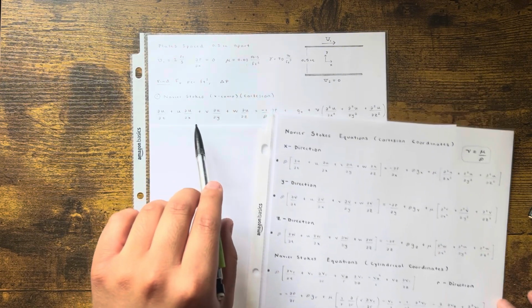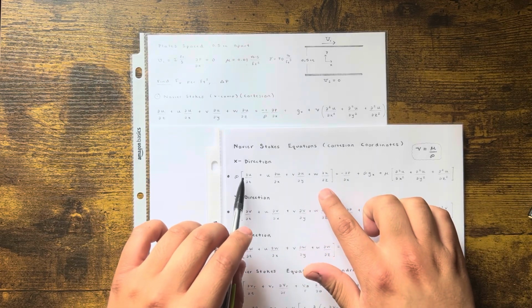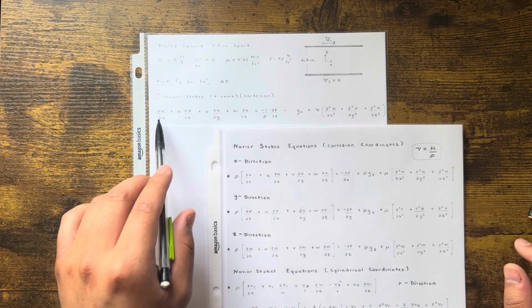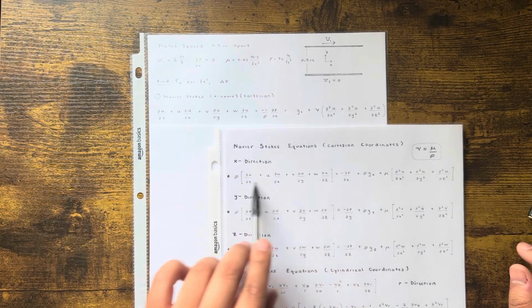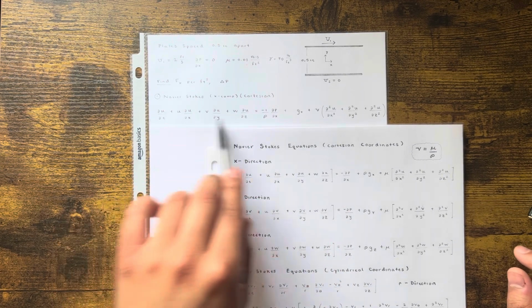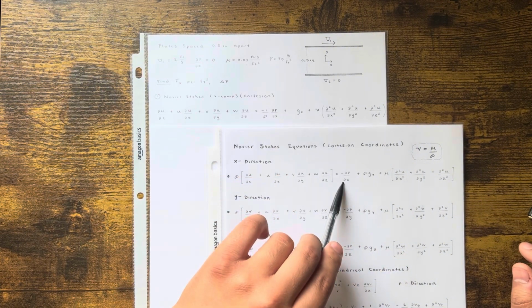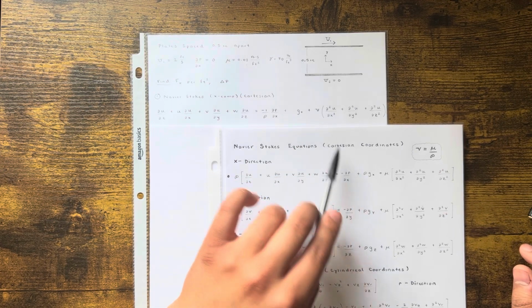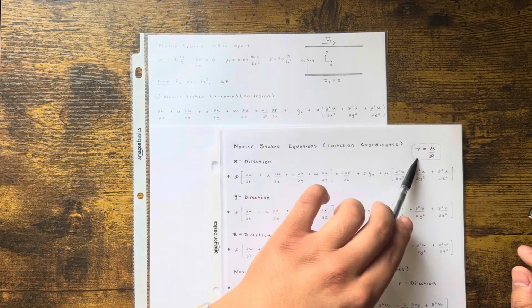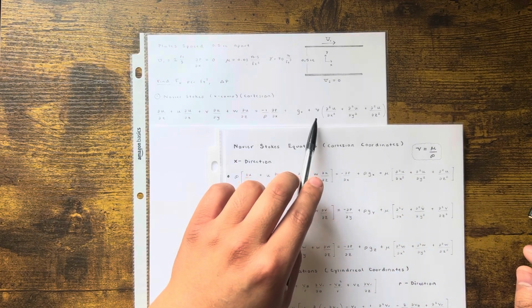Okay, that's what you see here, just a little modified. I like this version. This is the one that the book typically gives you. But all I did was just divide by density. Look at all these terms on the left side of the equation. They're multiplied by density. I just divided everything by density. That way, this becomes that, right? G of x, the density here goes away, right? And then the mu, the dynamic viscosity, becomes kinematic viscosity, okay?